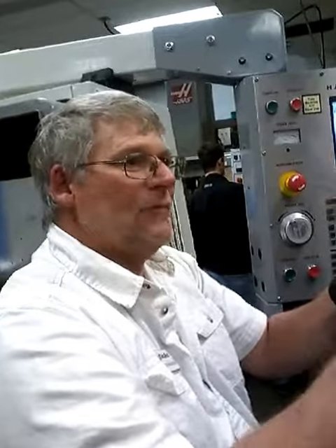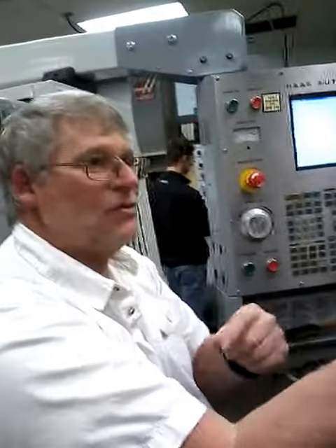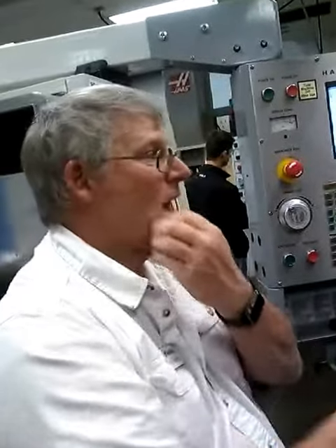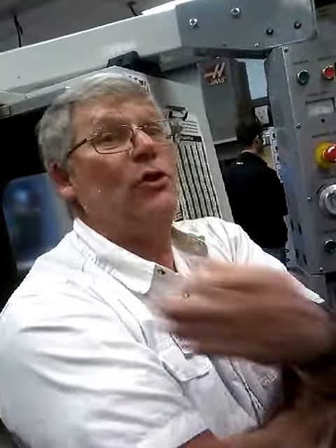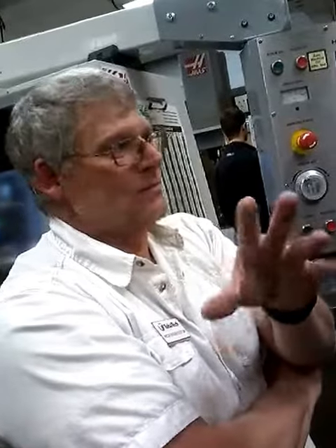So I could have the same identical program, with the only difference being this one has a G54, this one has a G55. And you can run the parts back to back. You can flip the part, right? That's what we do at work. I would need a new fixture offset. G54 is this, and then we flip it. And we'll talk in depth about some things that we're going to do.